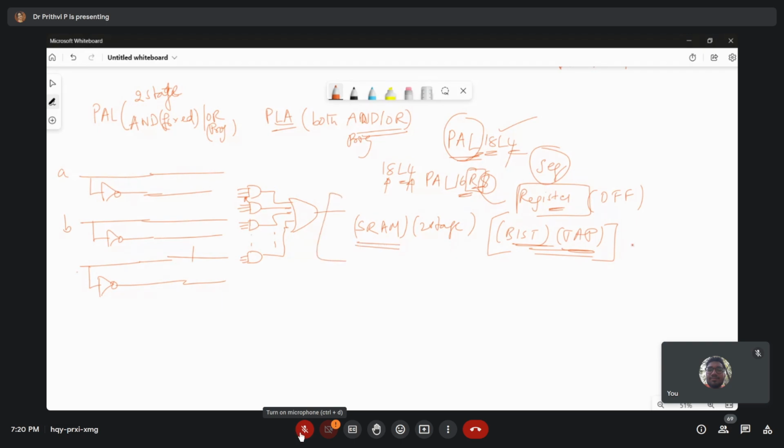All together, if you put these, this makes your FPGA. And here we are using anti-fuses. When you want to program them, we are saying these are two-stage things with AND-OR logic. We are using anti-fuse technology for programming the values of zeros or ones in your FPGAs.